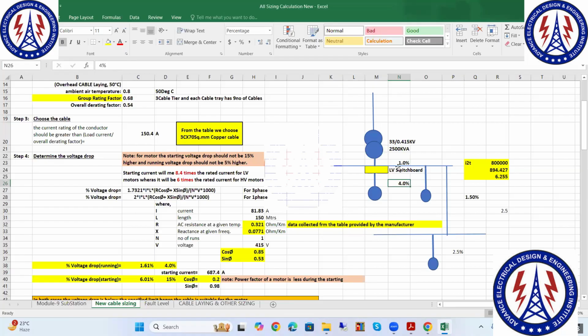Okay, we can do it 4 as well. This can be 4 and this can be 1. But the cable size will be different, meaning the cable runs will be higher in that case, and here it will be smaller. That does not look good, and it will be an installation problem. So if the length is higher, keep more voltage drop margin. In my case, that will be from panel to the motor. So it should be like this. But overall should be the same.